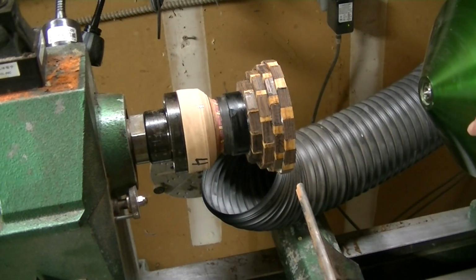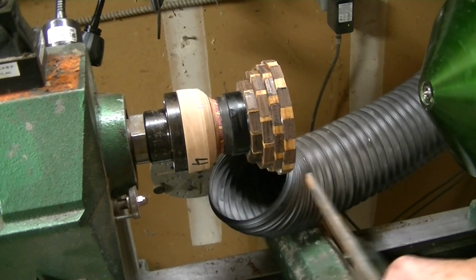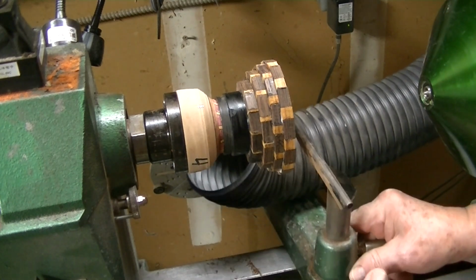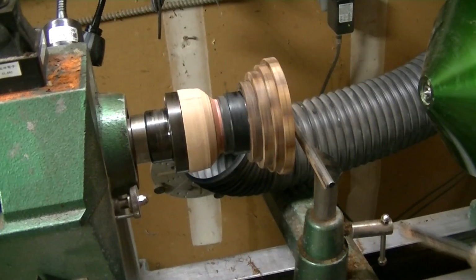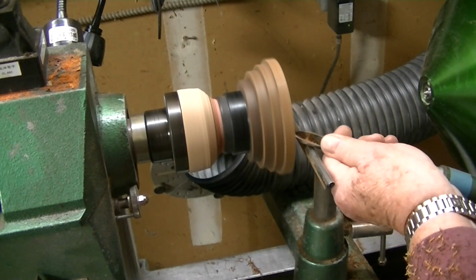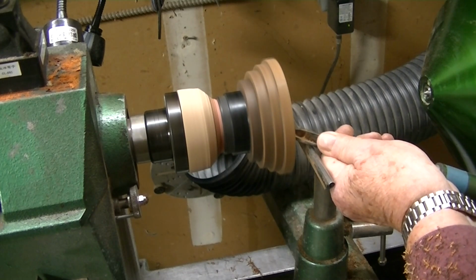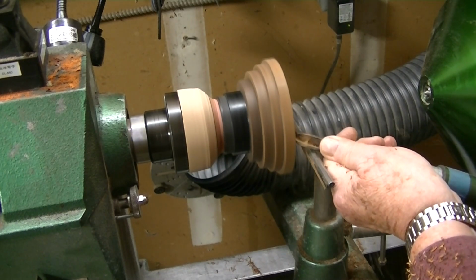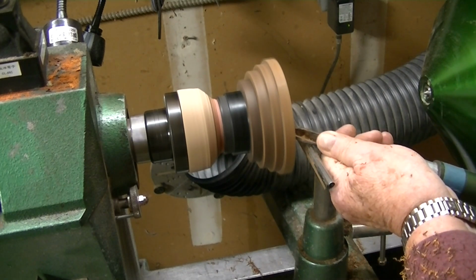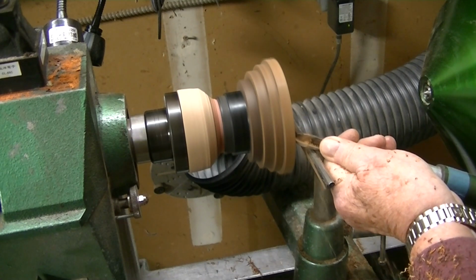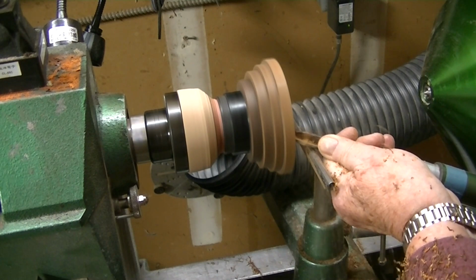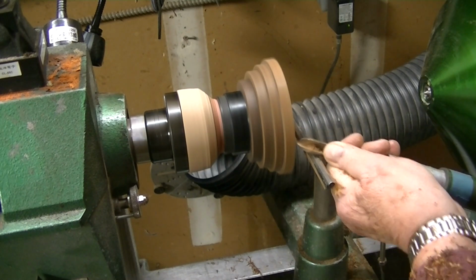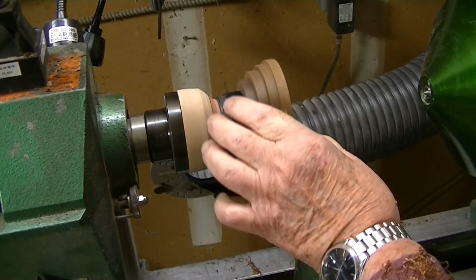Here's an assembly going on. We've added a few rings already, and now time to add the one we just saw assembled. So what I need to do first is to be sure that the assembly top is also dead flat. So a few passes with the bowl gouge to clean up any surface there. As soon as I'm certain that that is as flat as I can get it with a tool, I'll check it with a square.